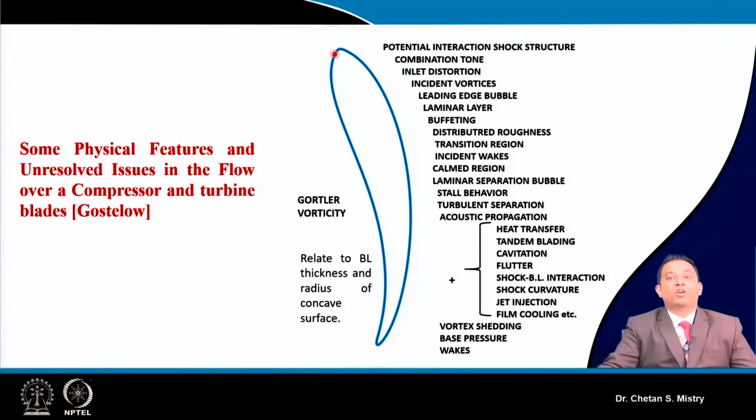That is what happens on my blade suction surface. In the same way, on the pressure surface we will also have growth of boundary layer because of the curvature. This aerofoil analysis is very challenging, and we must realize that part.